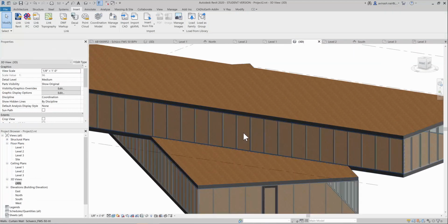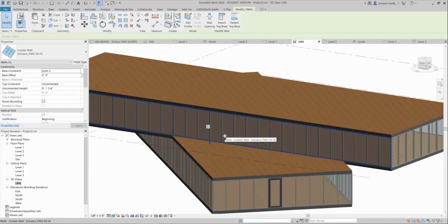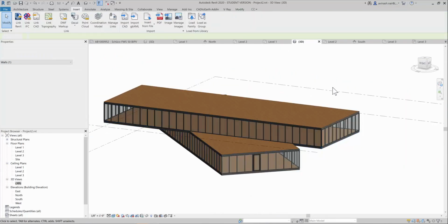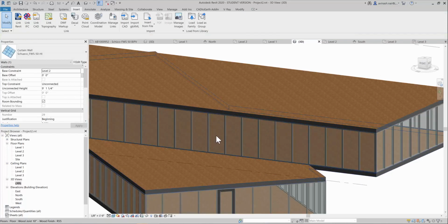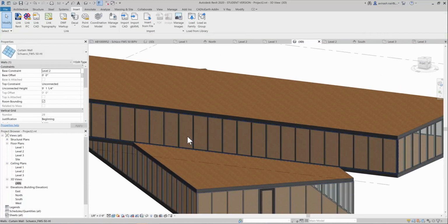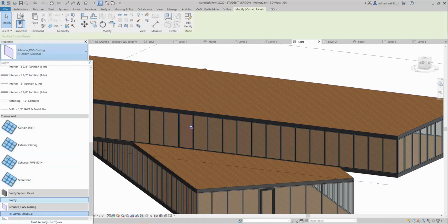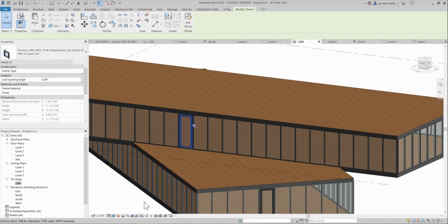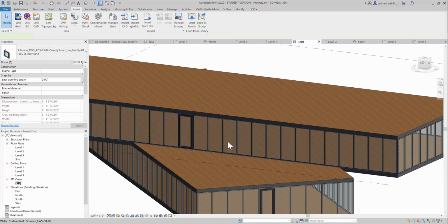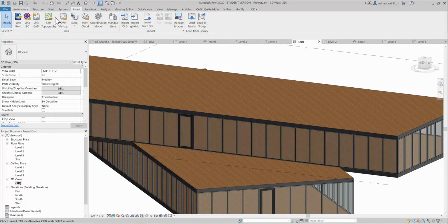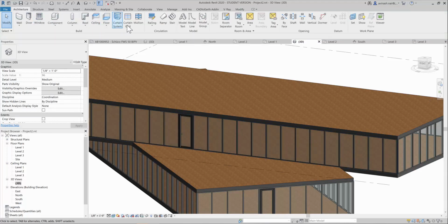And the same thing you can do here. I'll maybe try to integrate a window and a door on the top. I'll unpin this, and yeah, the same way you have to go here, put the door here, and to put the window, what you can do is you have to first create a transom.